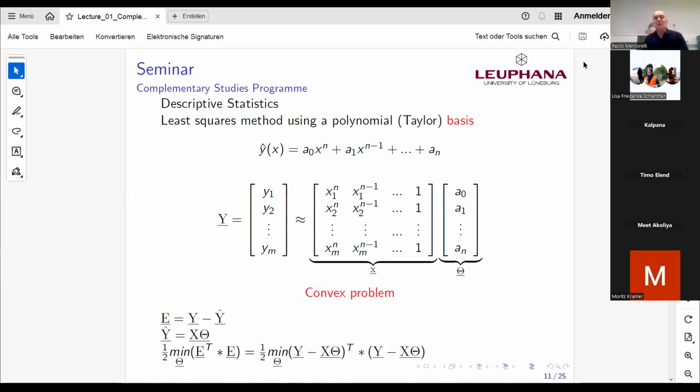If you look here, the parameter A0, if you think about our system, what we want to approximate is the flux of the motor versus the current. We have a current up to n. This means A0 is Weber divided ampere up to n. This means physically no particular meaning. Just to recall.